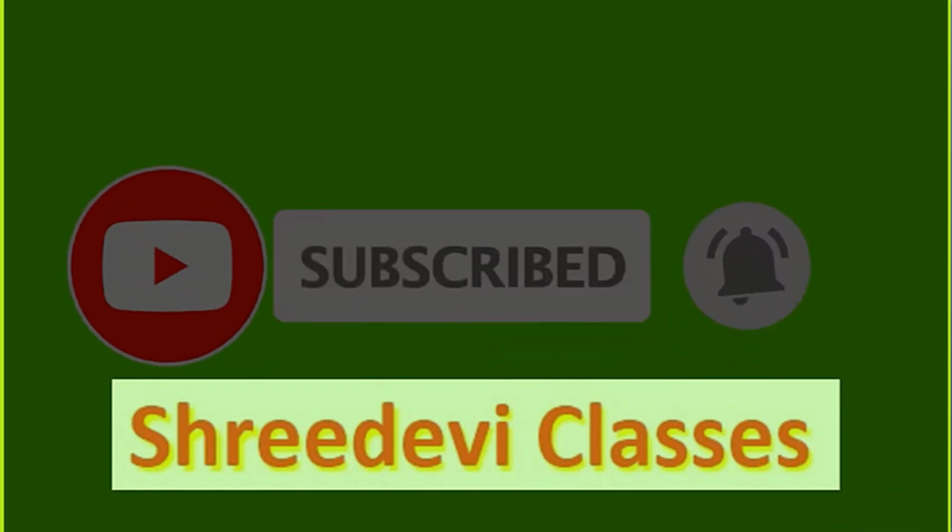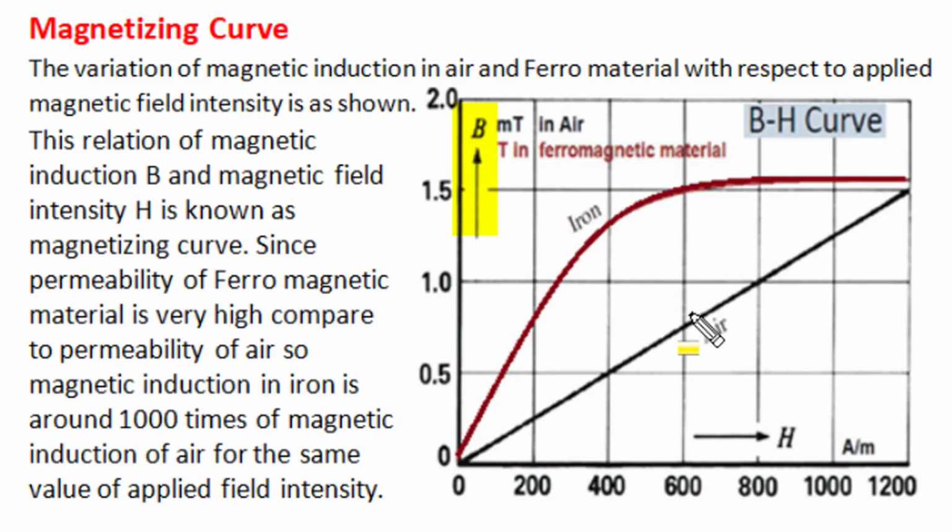Let's start the study of the magnetizing curve for ferromagnetic material. The variation of magnetic induction in air and iron material with respect to applied magnetic field is shown here. This relation of magnetic field flux density, or magnetic induction, with respect to applied magnetic field intensity is known as the magnetizing curve. Since the permeability of iron is very high compared to the permeability of air, for the same applied magnetic field intensity, the value of magnetic induction in iron is around 1000 times more than that of air.